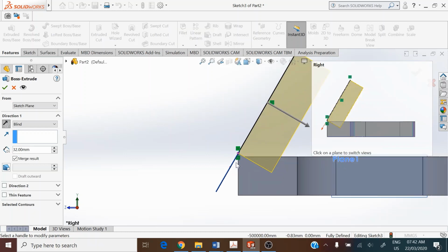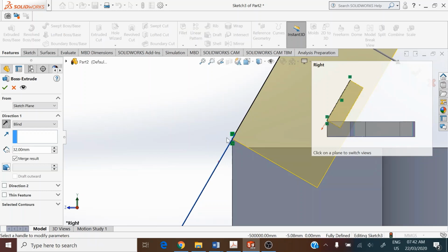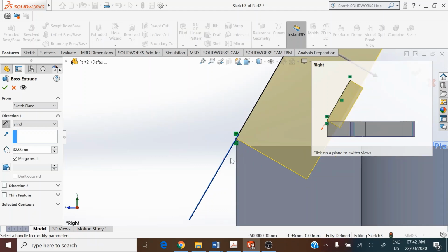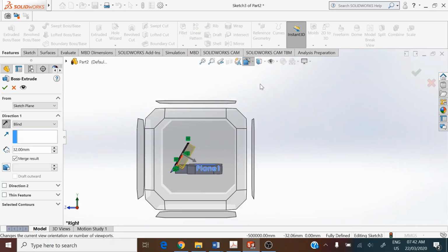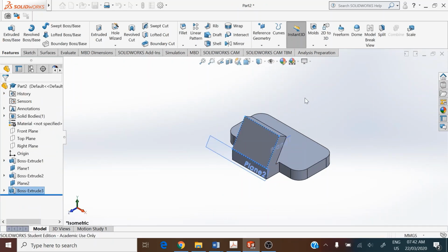Filling up, we have an extra portion here of the height going up to 35 millimeter and the angle 60° to make up the space that would come up due to extrusion at this normal extrusion of this slot body, normal to the sketch that has been made on the new plane. So that's the details which were described in the previous feature. Accept this to add the slot body.